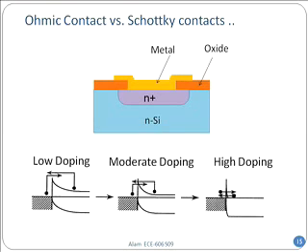Do you see, although it has a problem with those electrons, if you wanted holes to come in and out, you do not have a barrier for the holes to come in and out. Do you see on the bottom side that if the hole wanted to come in and out, there is no barrier? So the hole transport is always ohmic. Ohmic means linear dependence with voltage, no exponential dependence with voltage.